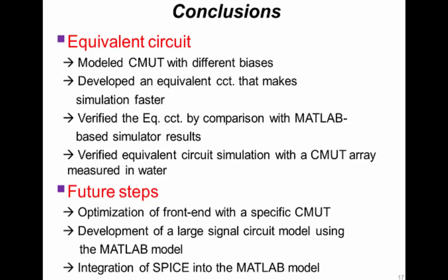So we modeled the CMUT as an equivalent circuit, and we verified the equivalent circuit with a MATLAB-based simulation and a measurement. And also, our future step is optimizing the front end based on this equivalent circuit and developing a large signal model, a large signal equivalent circuit.